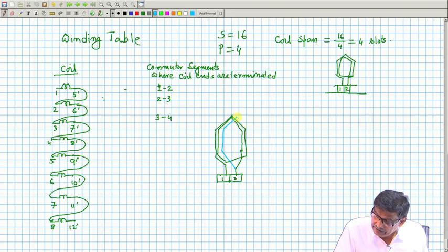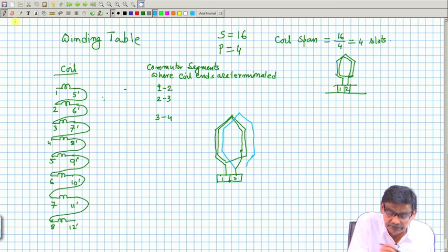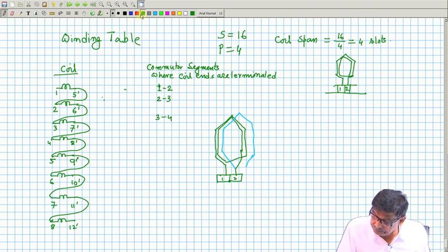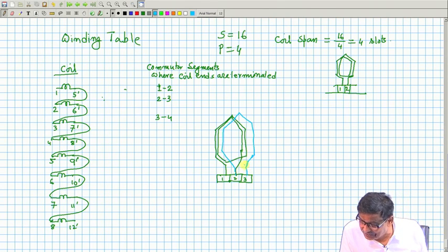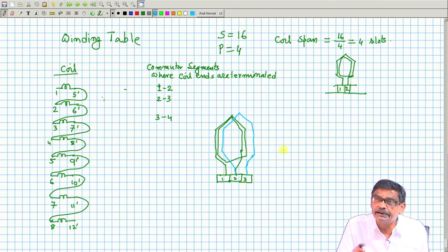So, next coil, first thing is commutator segment 2, this blue one, and its return will be terminated in commutator segment 3. So, from the junctions, those vertical lines are coming to the commutator segments, and because these commutator segments are connected to the shaft, they will also rotate.